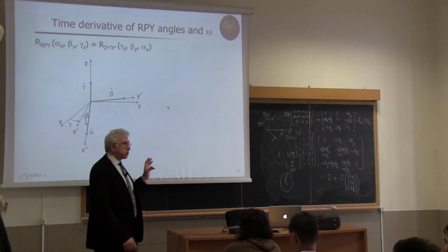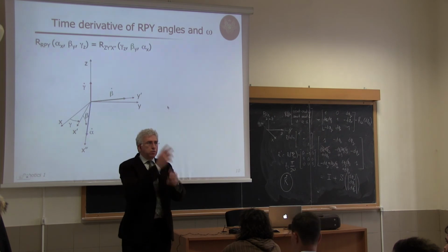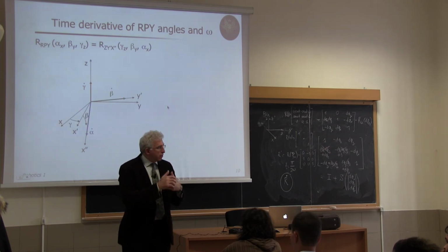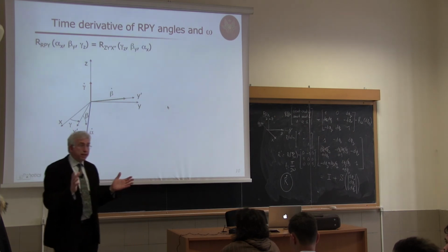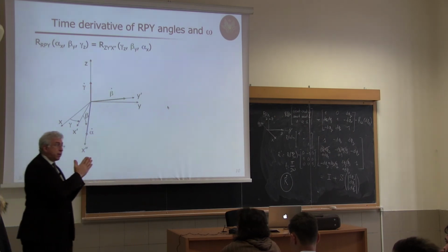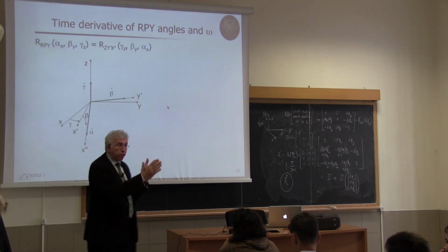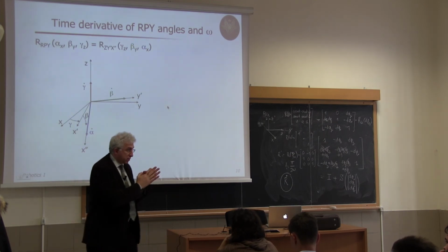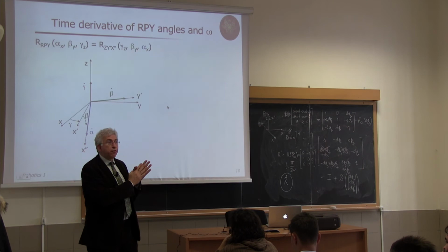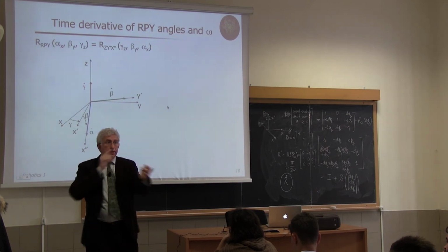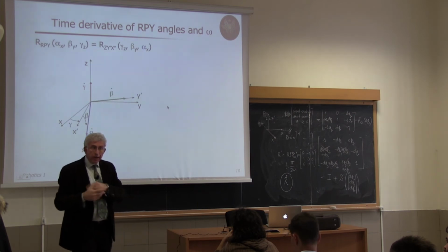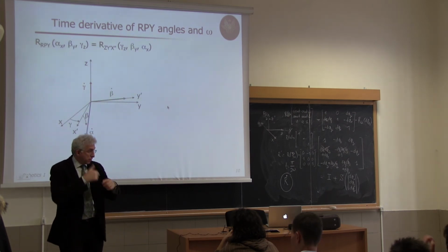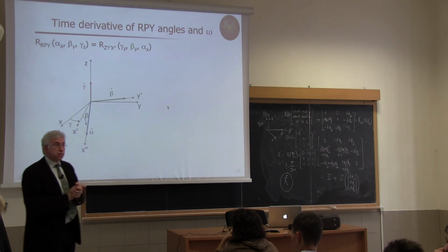Now, it's much more practical to look at this in the equivalent form of a sequence of rotations around moving axes. You remember that. Each of the 12 standard sequences around fixed axes is equivalent to another of the 12 sequences around moving axes. You have to reverse the order and exchange the angles.